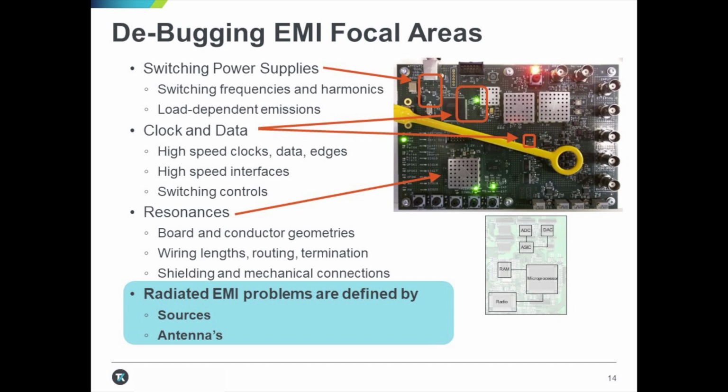Second, to switch mode power supplies and switching circuits, I often look at clock and data lines. Depending on the design, you may or may not be employing some form of spread spectrum clocking. It is important for us to know how well our spread spectrum clocking is working. After that is looking at a broad term I call resonances. Resonances could be actually in the board itself, could be in wiring diagrams, and could be in cabling, shielding, and harnessing issues.